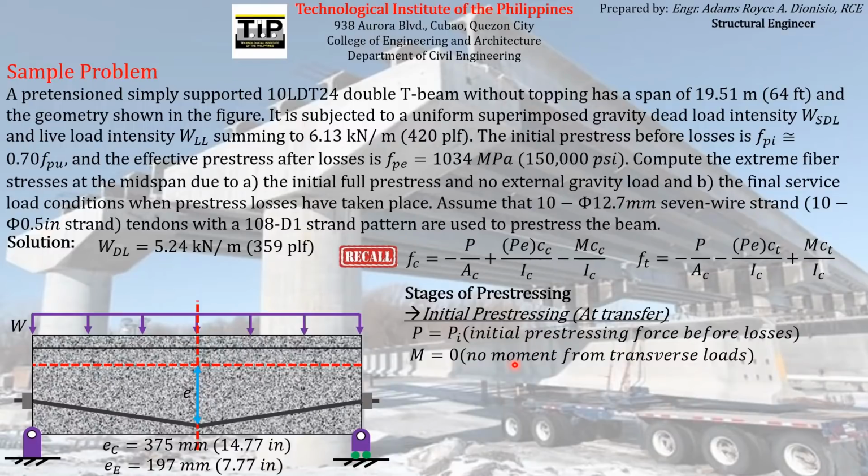After that, because of the eccentricity of the pre-stressing force, the beam tends to bend upward, thereby producing a camber. When the concrete is at that stage, we can say that it is at the initial pre-stressing at transfer with self-weight, because the camber, the scenario where the concrete element bends upward, forces the concrete element to support its own weight.